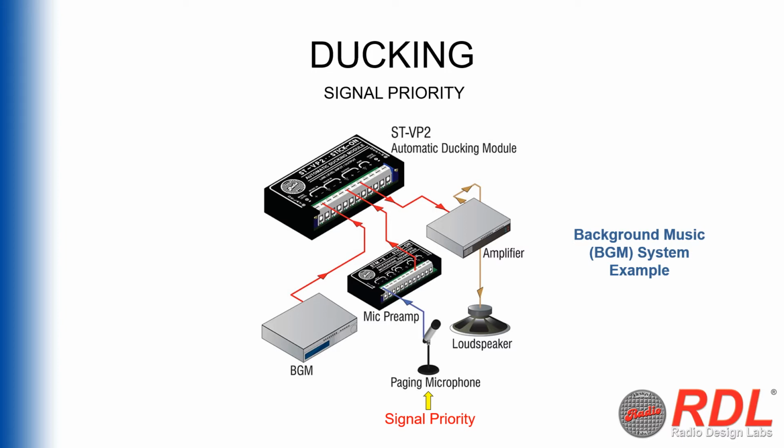This function may also include an adjustable time delay feature. A time delay postpones the restoration of the other signals, which helps prevent false stops caused by temporary absence of audio in the priority signal. Silent pauses at the end of sentences are good examples of this. Properly delaying the restoration of the less significant signals produces a smoother listening experience.